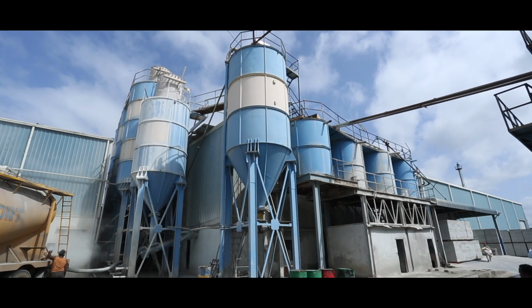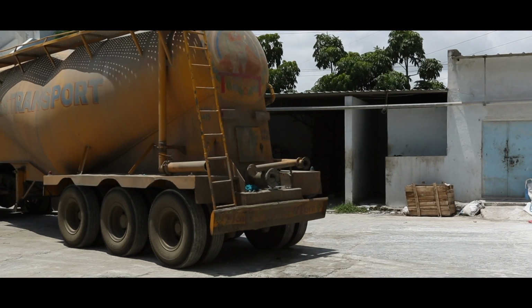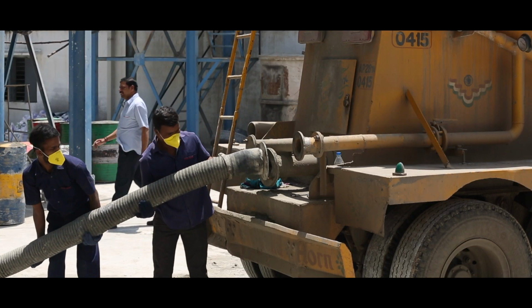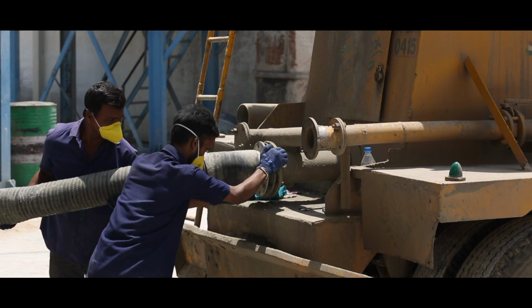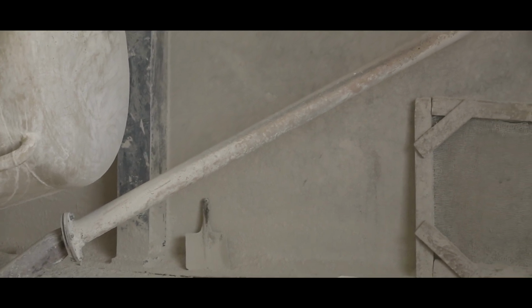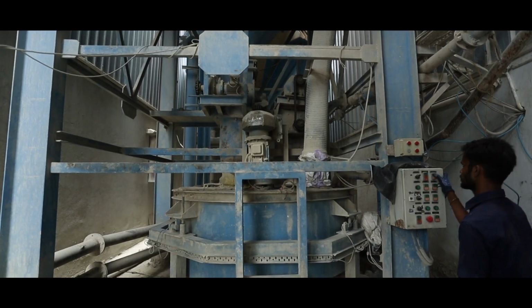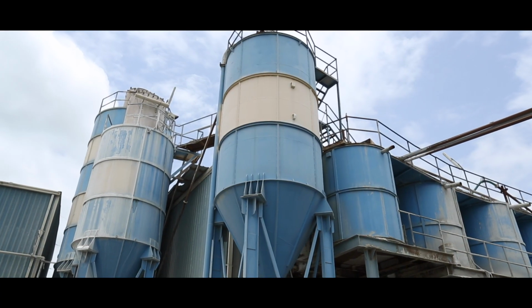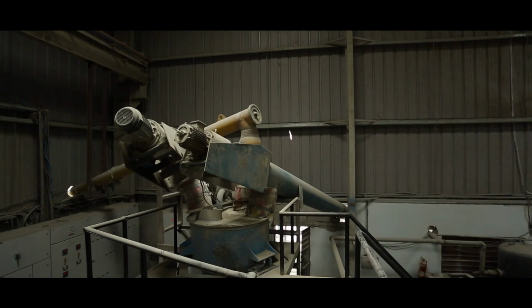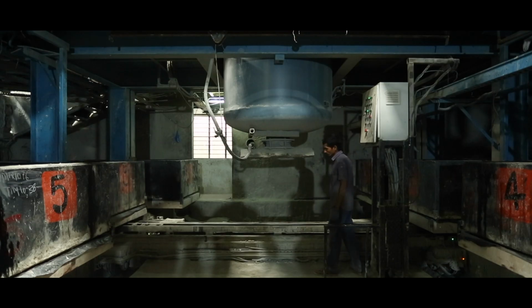The main raw materials for production of AAC blocks are cement, fly ash, lime, gypsum and a small quantity of aluminium powder. Cement and fly ash are stored in silos. Lime is processed by lime handling equipment. Fly ash is charged into a tank where it is mixed with water to form fly ash slurry. Pre-measured quantity of fly ash slurry is pumped into a process mixer. Cement is fed into the mixing tank, so also pre-weighed quantity of lime and gypsum. Aluminium powder is received in tins and a small quantity is added into the main mixer to form a slurry.